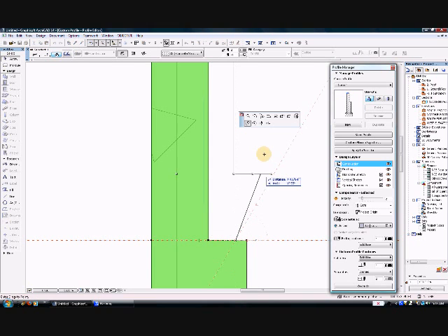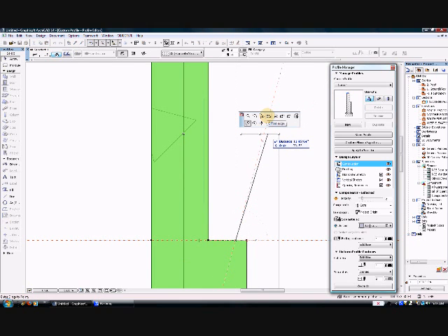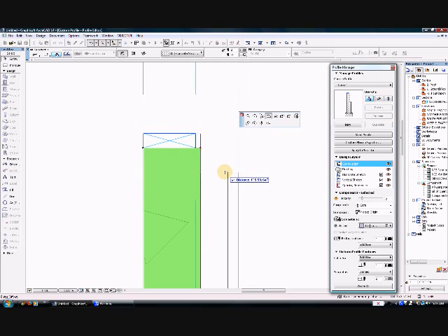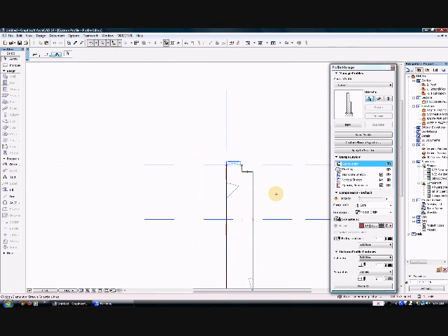So we'll click on that edge, and if we go to the pet palette, we'll find the Offset Edge button, at which point we can raise that edge. We'll pull up, type in 18 inches, enter, and we've made our adjustment. The second adjustment we needed to make was we needed to move the entire wall in about 5/8 of an inch to line up with the wall on the first floor.